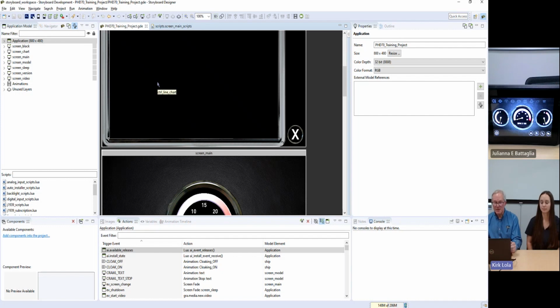As the application is being developed, the programmer can simulate the application in the Crank environment without any hardware in the loop. This saves debugging and development time by eliminating tedious back and forth: downloading to the hardware, checking the functionality, changing the software, and going back and downloading to the target hardware again. So this greatly reduces development time.